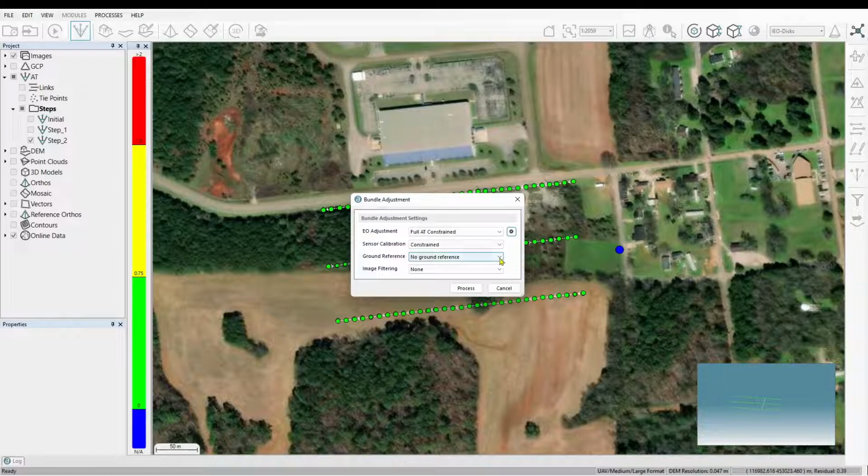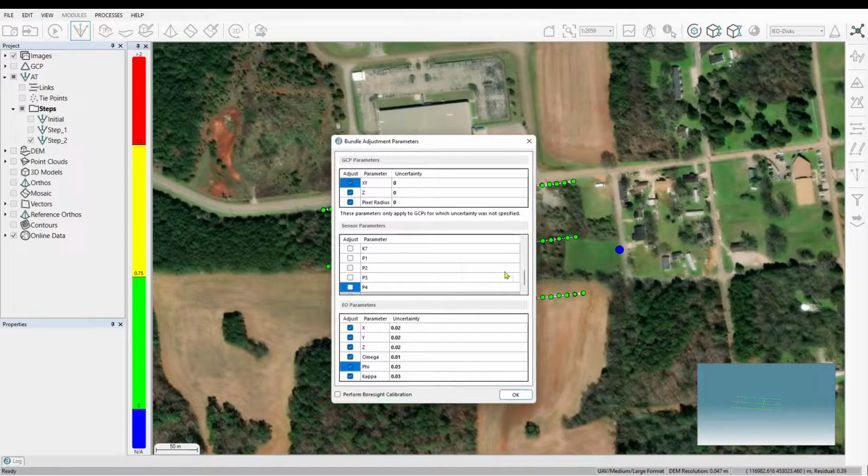You could also, again, add ground control points in. So say if you measured ground control points, you could see it now adds this up here as well. And this is your uncertainty on your ground control points. You may have a little bit of uncertainty there in your X and Y or your Z, and you could say, I've got 2 centimeters uncertainty there.